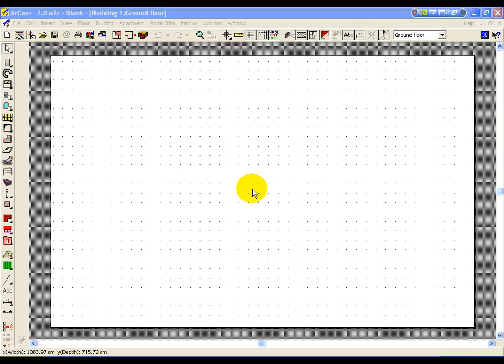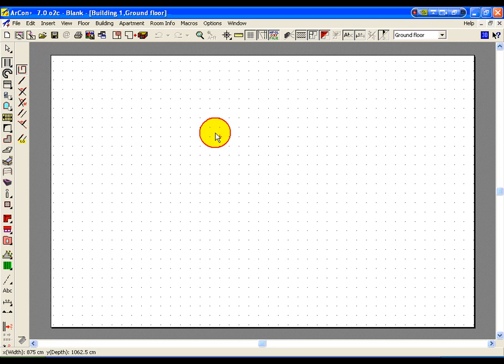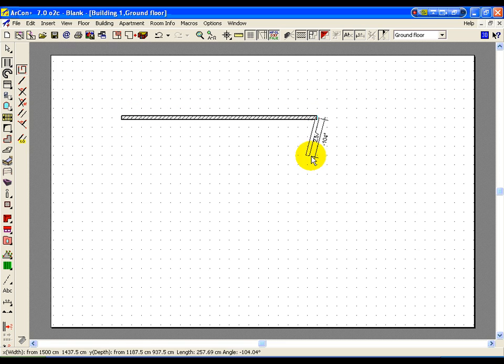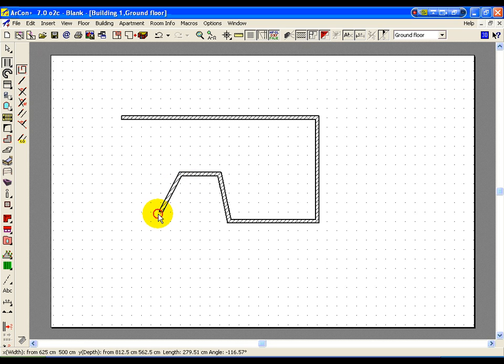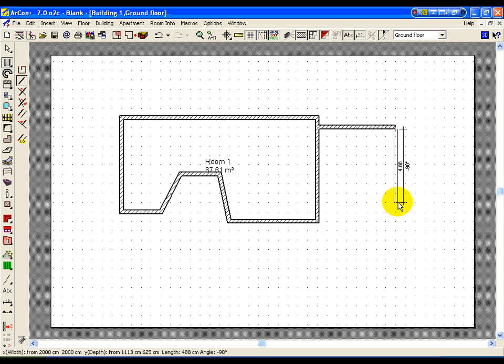This tutorial concerns walls. Walls are created from the wall icon here. So I've actually used the chain wire method of inserting a wall, replacing single walls. I'd have to create 2 clicks for each wall. Putting a wall at right angles to an existing wall, I select an existing wall and the wall is dragged out at a right angle.